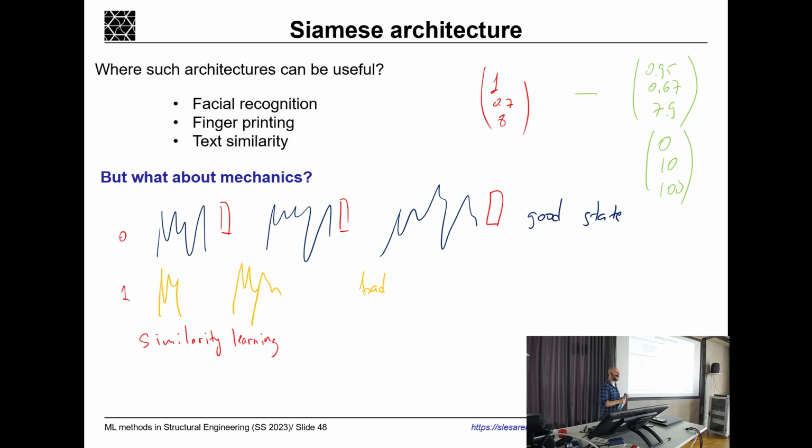Kind of, I would say, good luck with that, because even when you check the data, you do not check the signal in the time domain. You probably do a Fourier transformation, so you already do some processing of your data. Then any smart engineer will look at this and say, okay, we should not have this peak at a frequency of, let's say, 1 kilohertz. So you're doing the same thing, but without using machine learning.